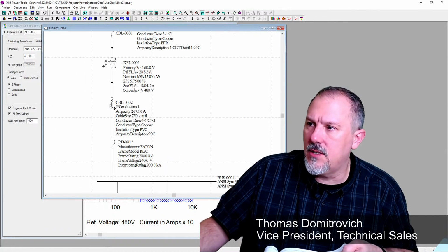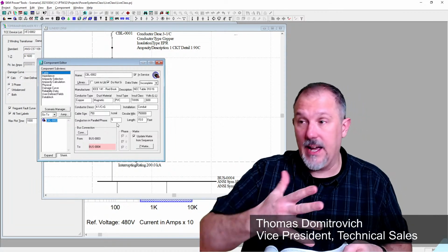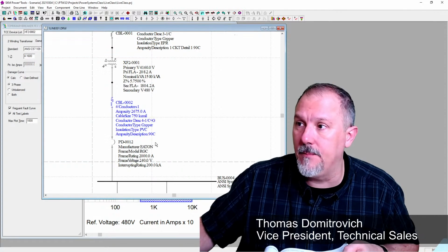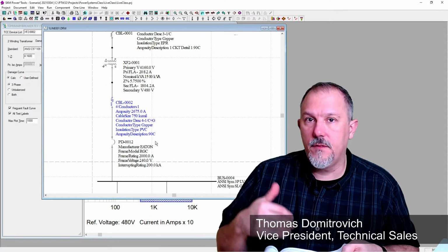Okay, let's look at this one. I've got 5. Okay, I got 5 750s. I need 2,000 amps. I need 2,000 amps worth of conductor.